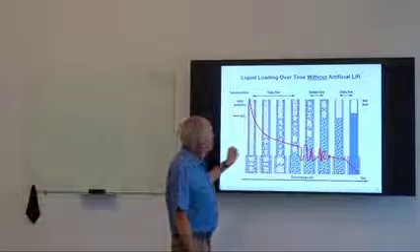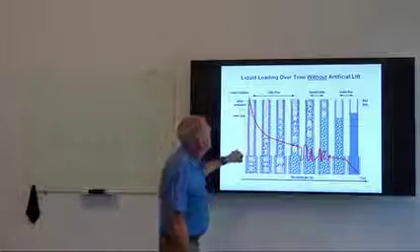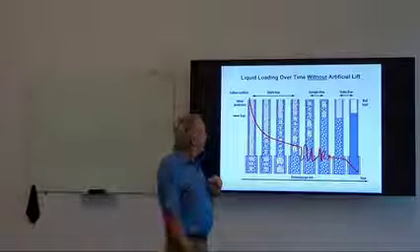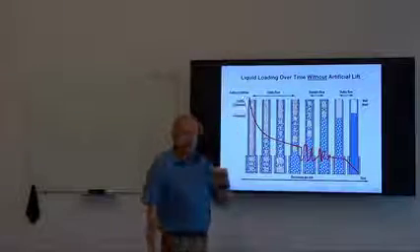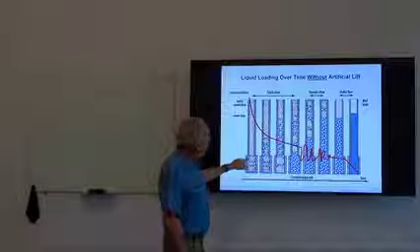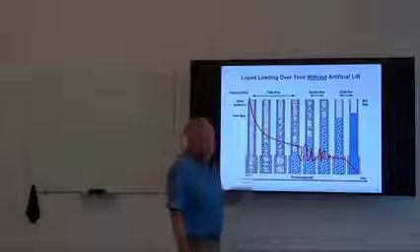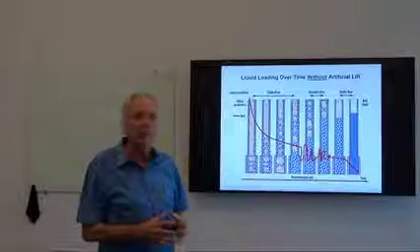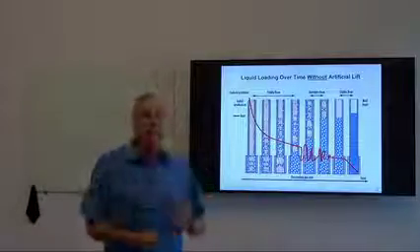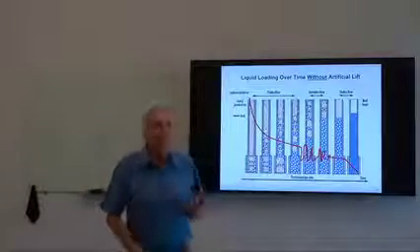So when that well is brand new and it's young, it's strong, we have a very high flow rate and initial production rate. We have a very high velocity of gas, or relatively high velocity of gas, throughout the depth of the well. And that velocity is carrying the liquid to surface.